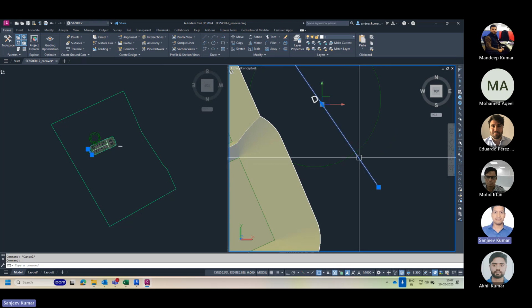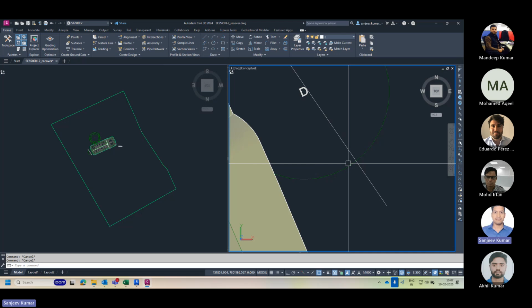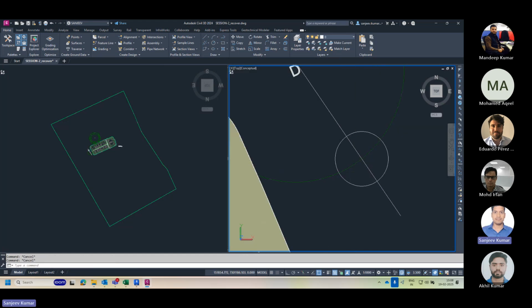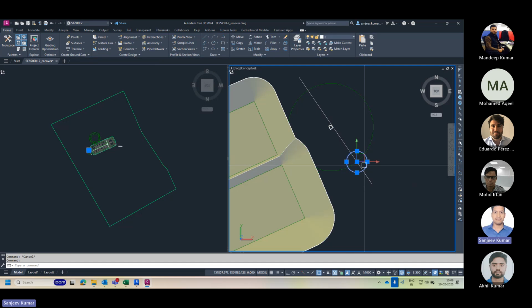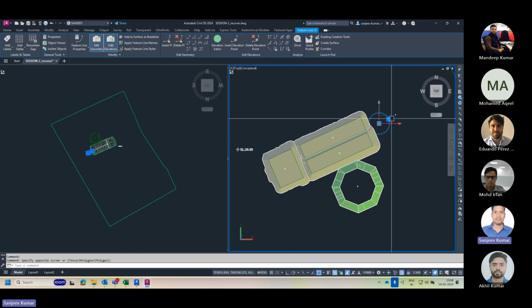So when we give this one an elevation, we have a point that is created at this point. That one always sticks with this one. So we have a problem putting both of them in a single site. So we suggest creating a different site for the different entity or different places.